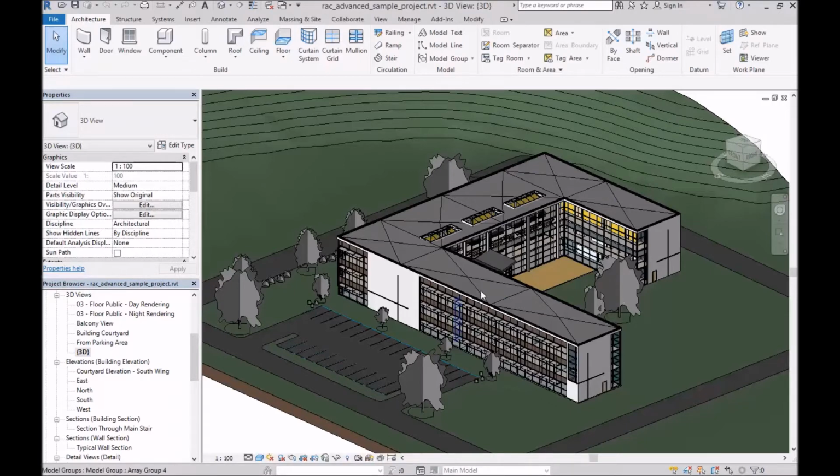There are two big categories of issues we often see with Revit models. The first is modeling issues, elements that are modeled with the wrong family type or the wrong function type, and these are fairly easy to check and fix. The second set of issues are regarding plane counts. A lot of shading or glazing planes will cause the energy analysis to run very slowly, and if you have an excessive number of planes, the analysis may time out. So there are a few things that we'll cover that drive up that plane count significantly, and we'll go over how to address those. But let's get started with modeling issues.